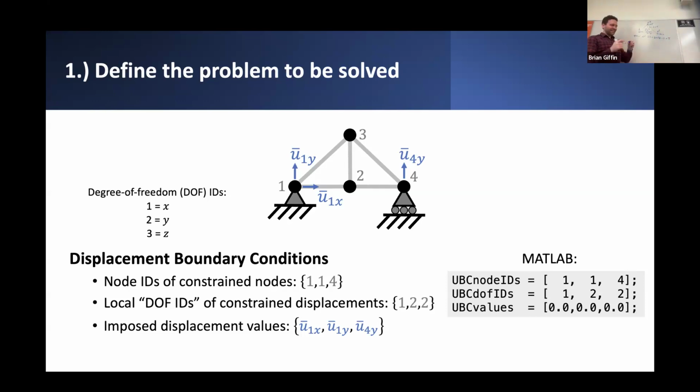And you'll see that I use this implicit numbering scheme throughout pretty much the whole rest of that MATLAB script. So implicitly, this is what's happening behind the scenes. But you can rationalize that this particular numbering scheme arises from this particular choice of offsetting things. So I'll encourage you to take a look at that in more detail. But obviously, it implies that the way that you index and order these degrees of freedom becomes more complicated as you introduce more degrees of freedom per node.